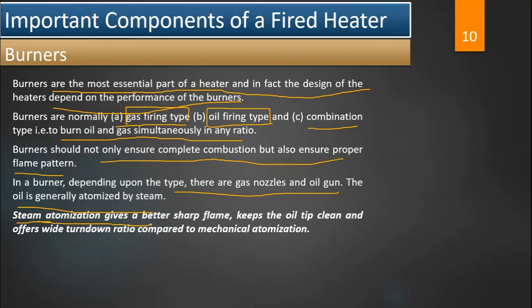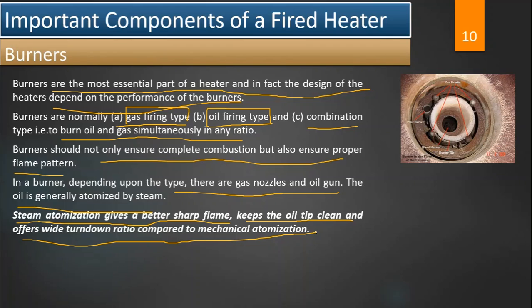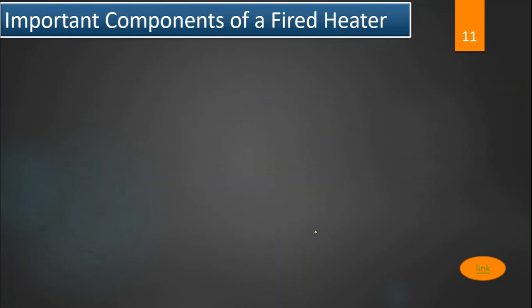We have two options, either steam atomization or mechanical atomization. But steam atomization gives a better sharp flame, keeps the oil tip clean and offers a wide turn down ratio as compared to mechanical atomization. So that's why we prefer it. This is one simple diagram of the burners.